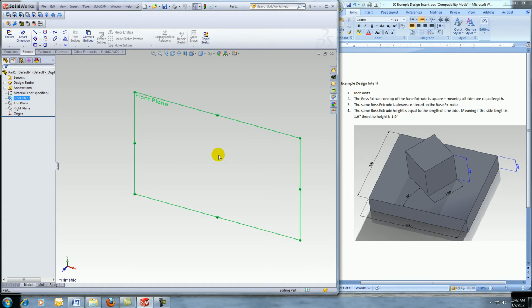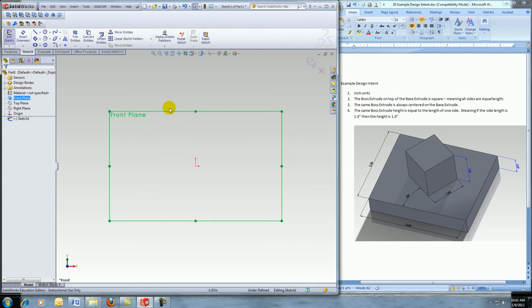So I'll pick this plane, and I can go to Sketch. For example, there are a couple different ways, but I'm just simply going to pick on Sketch. It orientates the plane, so I'm looking straight down at it. Remember, it gives you this 0, 0, 0 space out in 3D with the 3D world, and that is my 0. And so my first dominant shape looks like a square or a rectangle. It's rectangular because these aren't the same dimensions. But it is vertical and horizontal.